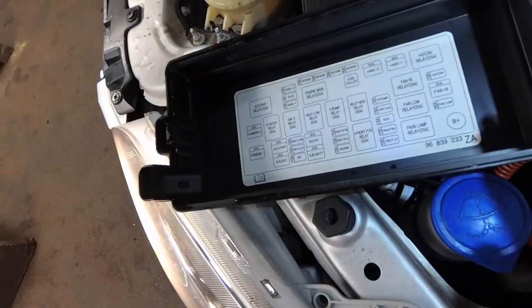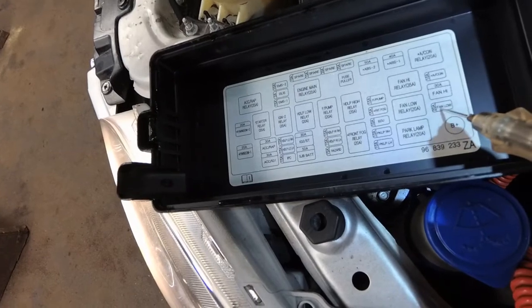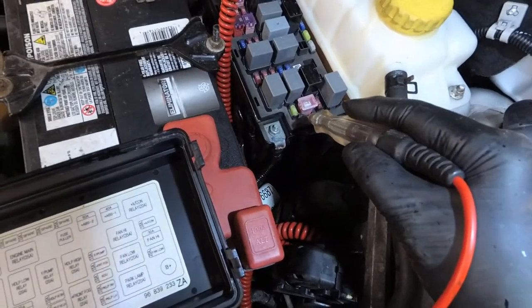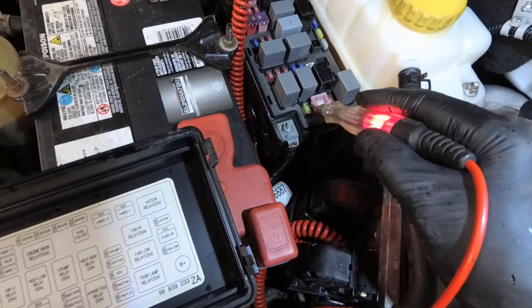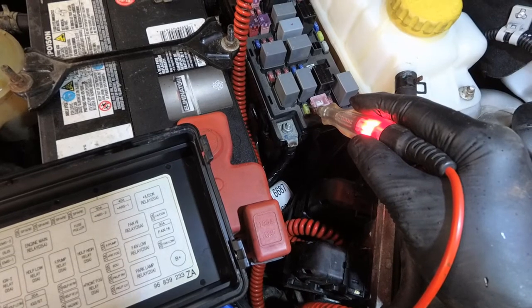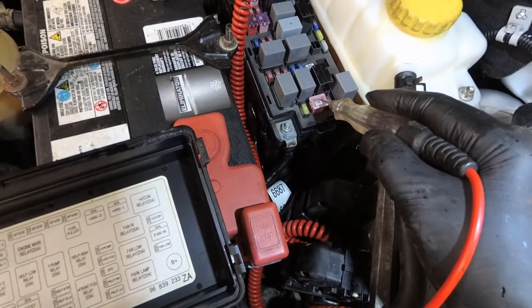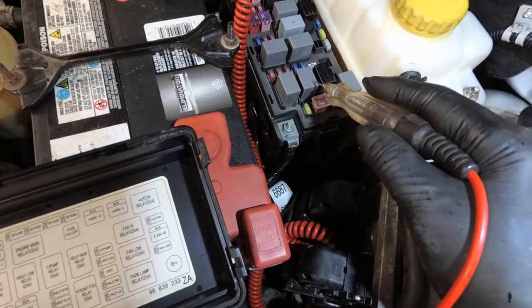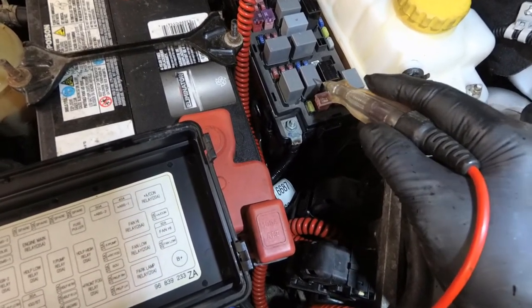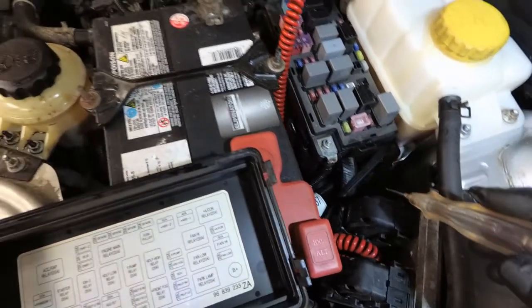So in the schematic it called it fuse 24, but on here it doesn't give a number. It just gives low-speed fan low, which is that fuse right there. Key on. I got power on both sides of that fuse, and this is fan high, and this is the fan low relay, fan high relay, fan low relay. So we'll find that dropping resistor.